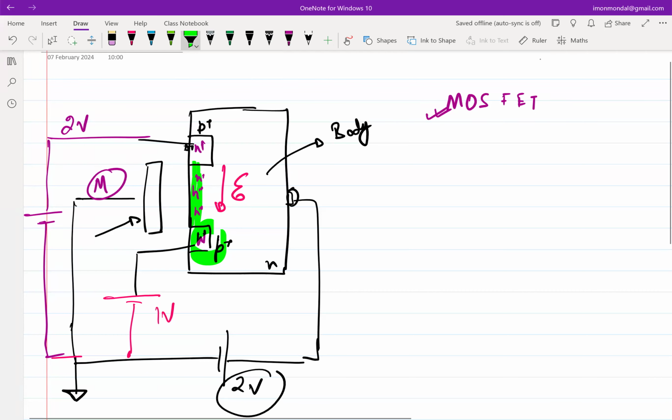As you should recall, this region here is a dielectric, right? You cannot have things hanging. You have to put something there. The most reliable dielectric, in terms of its longevity and electrical and mechanical properties on a piece of silicon, is silicon dioxide. So this is not a vacuum.